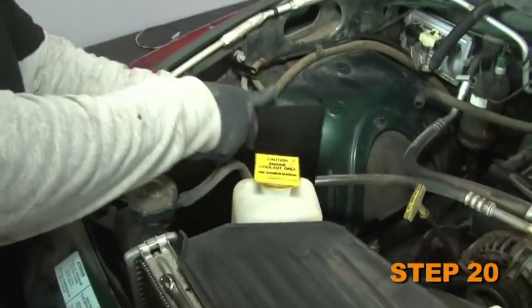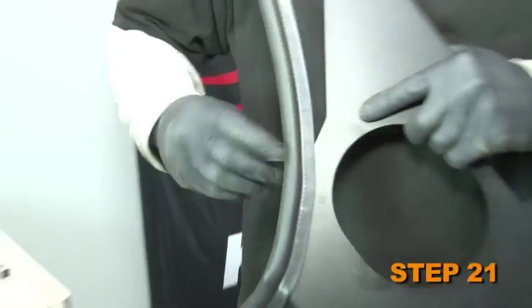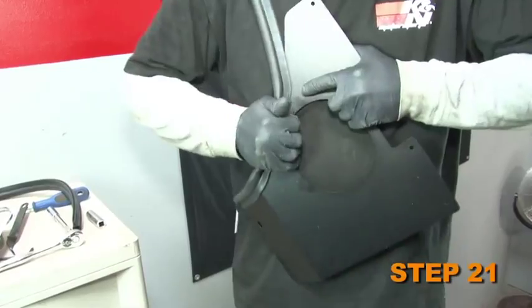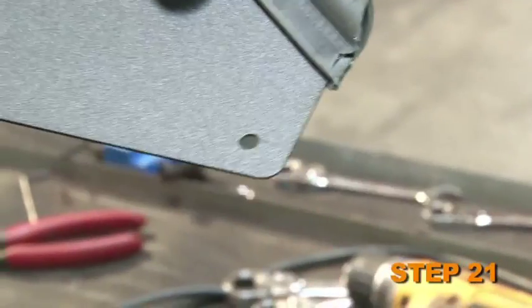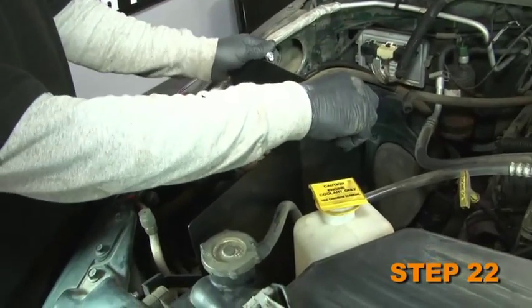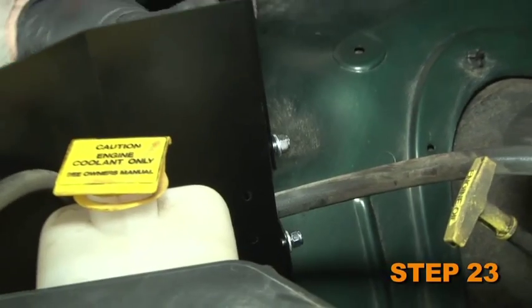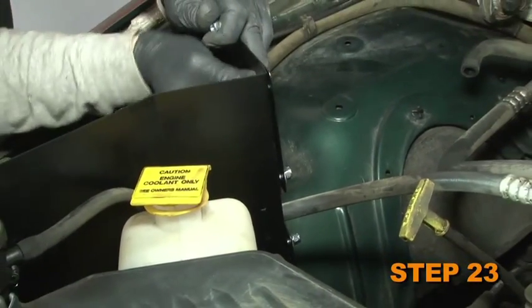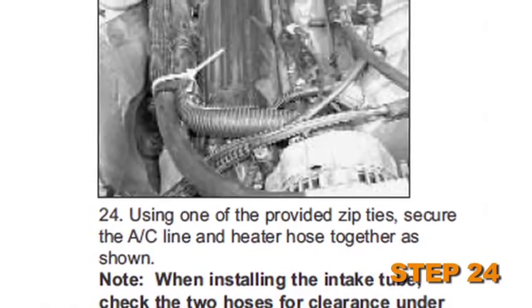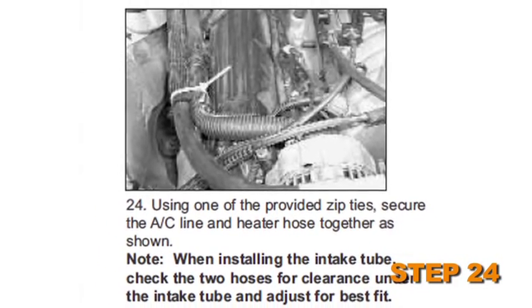Install and secure heat shield B to the Z bracket, but do not tighten completely at this time. Apply the 18-inch long edge trim to the heat shield and trim as needed. Install and secure heat shield A to the long L bracket, but do not tighten completely at this time. Secure heat shield A and B together. Using one of the provided zip ties, secure the AC line and heater hose together.